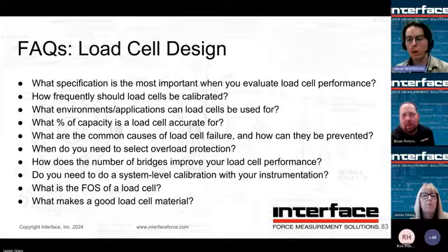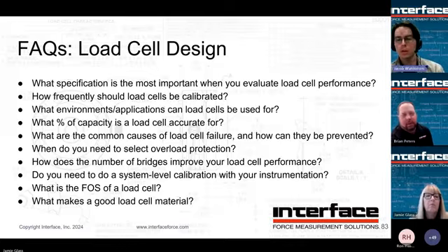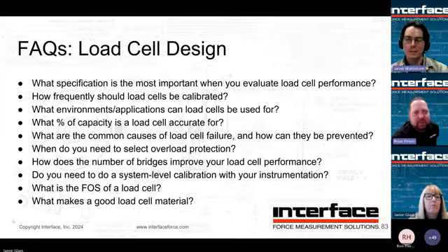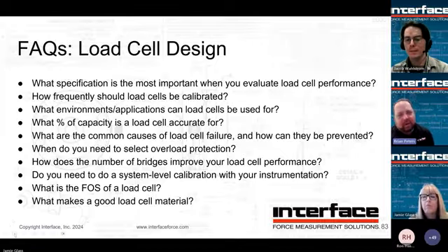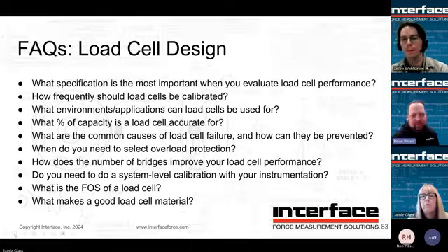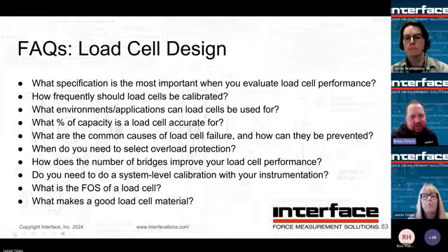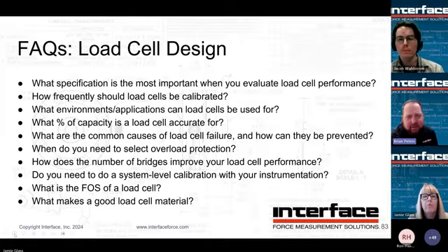Then Brian, what makes a good load cell material? Typical answer: it depends, right? Depends on the capacity, depends on the application, the environment. As long as it's communicated, we can pick the right choice. But I think in general, we talked about good load cell materials should have high stiffness, hardness, act like a good spring. That's the key thing. Otherwise, you're going to run into linearity and hysteresis challenges. So, all right,